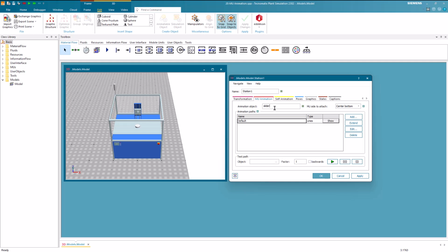Using coordinates is preferable when the position where an object should move is calculated. An example of this scenario is the portal crane from the Cranes and More library, where the portal needs to be precisely positioned based on calculations or dynamic factors. On the other hand, poses are more suitable when you have a static and predefined position in mind. In cases where the object's location remains constant, poses provide a straightforward and efficient means of defining and managing these positions within the simulation.